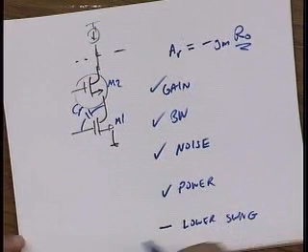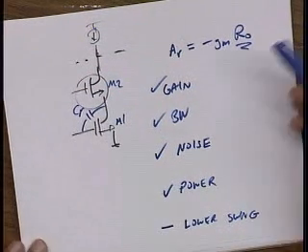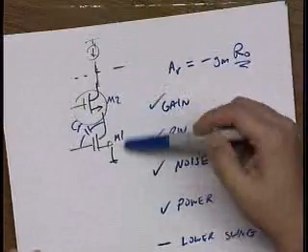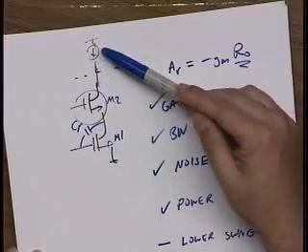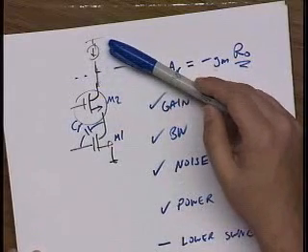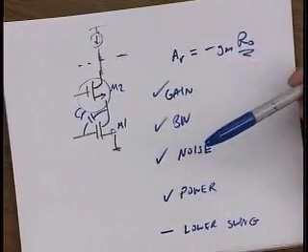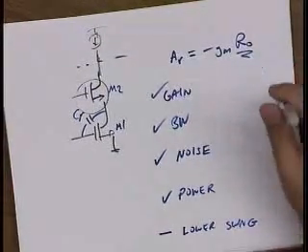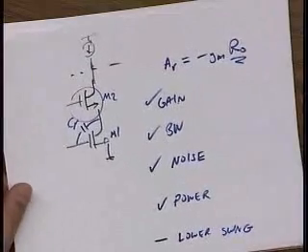and that's definitely something to consider as we go into deeply scaled technology, because as it turns out, not only do you have the swing limitation of this cascode, but of course to get the high gain you're going to have to make this current source also a cascode, so then you're really going to suffer from voltage gain, and we're going to talk a lot more about that in today's lecture. Okay? Alright, so let's go back to the slides.